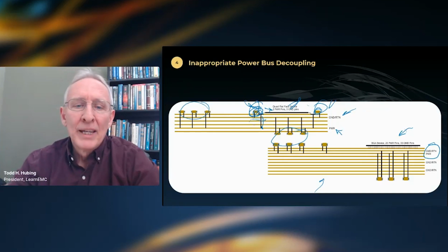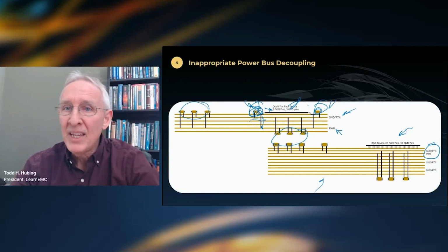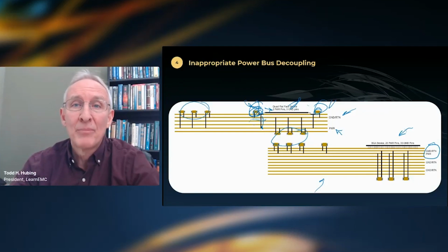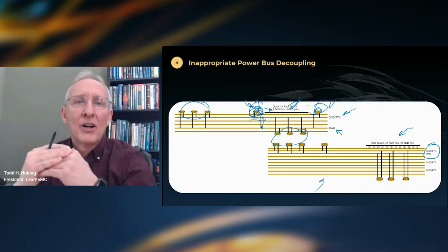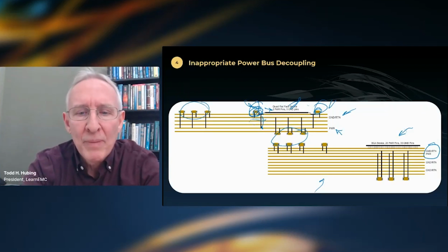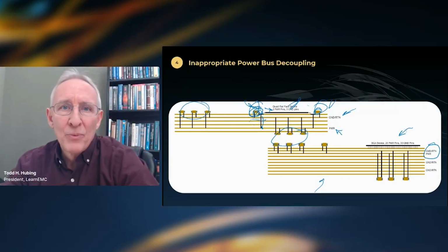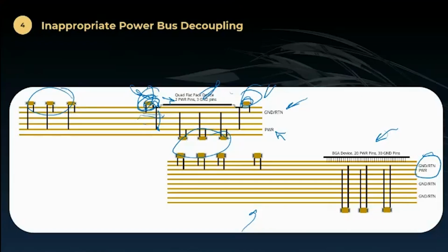Now everything's different. We can't decouple each one of those power pins, and we don't want to. Basically, when they need charge fast, they're getting it from that plane capacitance. And all of the decoupling capacitors on that board are waiting to see the voltage in the planes drop, and then they are providing charge. If we look at this particular case, which capacitors are responding first? Which are supplying the most charge when that BGA device starts to deplete the charge in the planes?